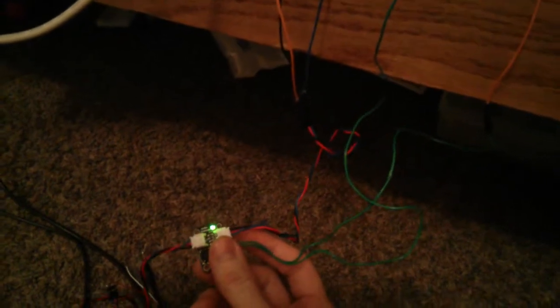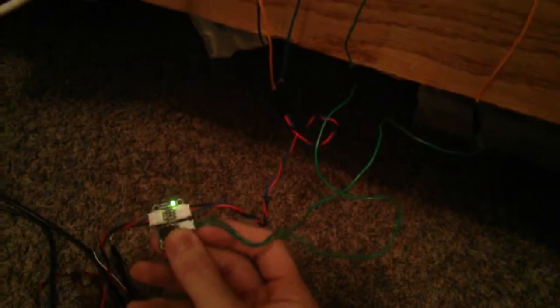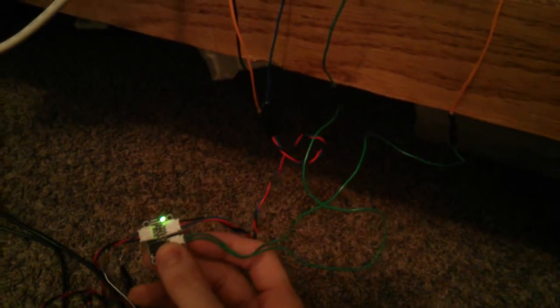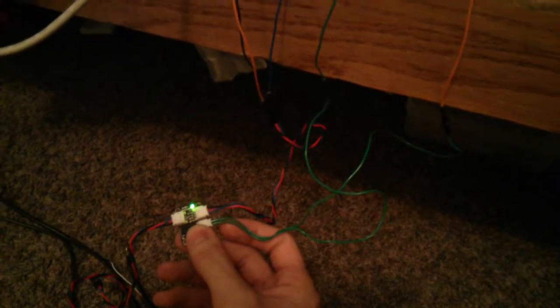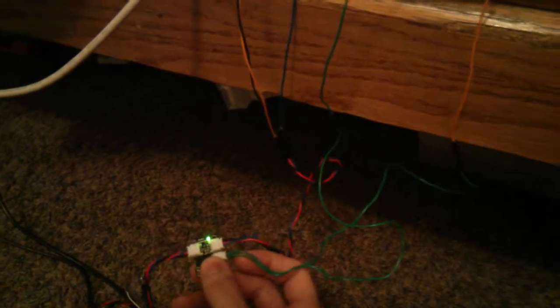On the top right here, there's 5-volt DC power, ground, and also the analog into the Arduino, that blue wire, which is the output of the MSGEQ7. These 2 green wires are strobe and clock. Clock advances it to the next frequency component. Strobe starts it back over at the first frequency component, so like does a new line basically.